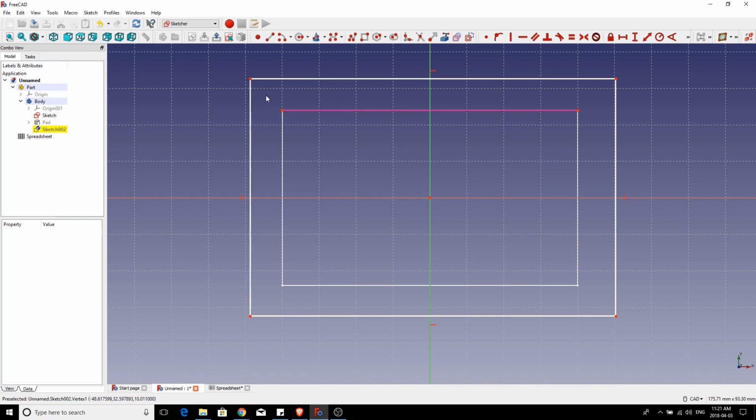We can start putting a constraint on this box right here. So if this is our credit card, and we are now cutting our inside wall for our box, what dimension are we going to need to use? It's going to be the offset, that little 2 millimeters clearance that we're leaving around the outside edge of our card. So let's do it parametrically.